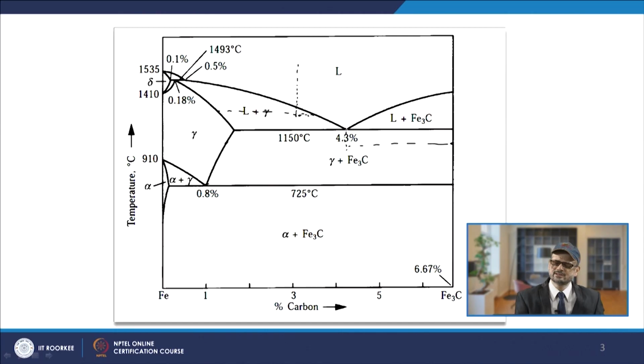Now, what we see is that we have understood that in this case, when we take the carbon more than 2%, normally we call it a variety of cast iron. Now, in the case of cast iron, the carbon which we see normally is in the form of graphite. So, when you are cooling in a slow manner, graphite is a stable structure basically, and Fe3C is metastable.